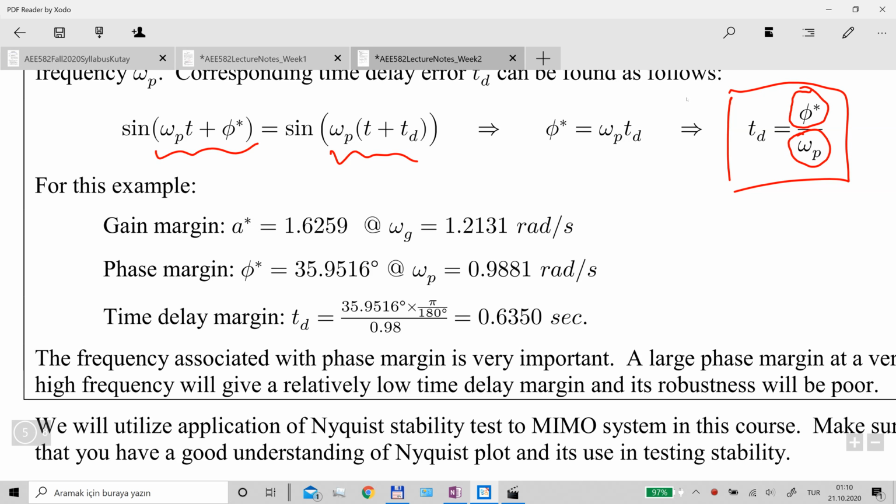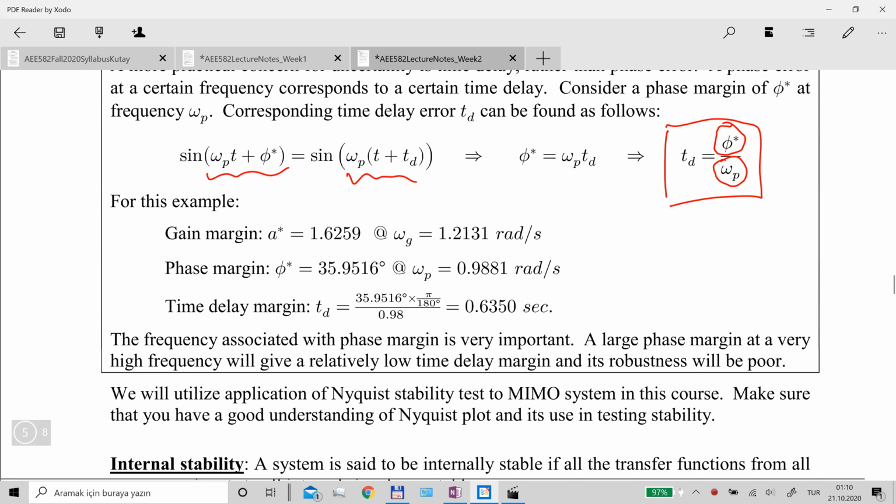In the earlier videos, I told you that in robust control, we combine the benefits of classical control and modern control. In classical control, we have some powerful frequency domain techniques, and this is really what I meant by that. We can assess the uncertainty or robustness of single-input, single-output systems using this Nyquist stability test. But here we cannot really study multi-input, multi-output systems, so this is only true for single-input, single-output systems. In modern control, we use state space representation where we can handle multi-input, multi-output systems easily. But here we don't have such easy ways of checking the robustness of the system. And in robust control, we combine the benefits of these two.